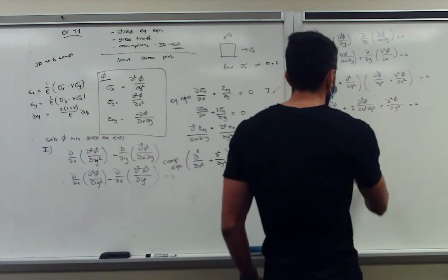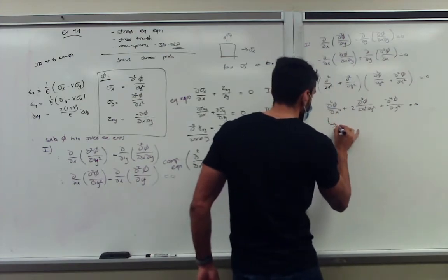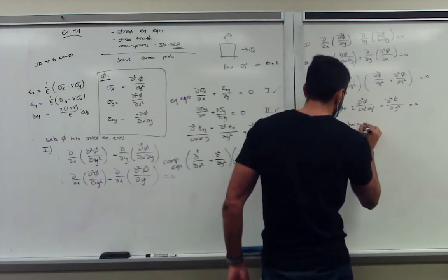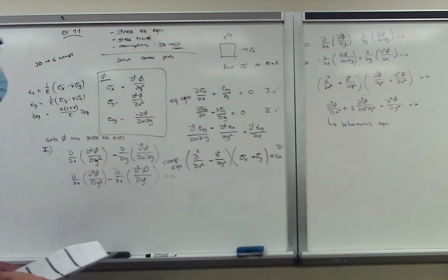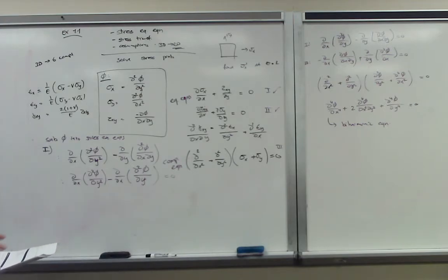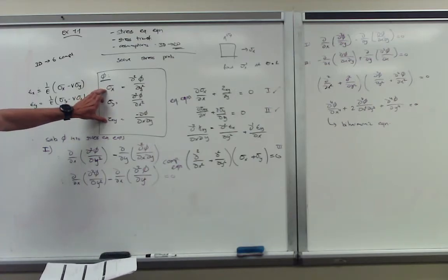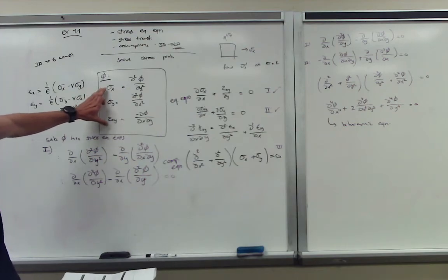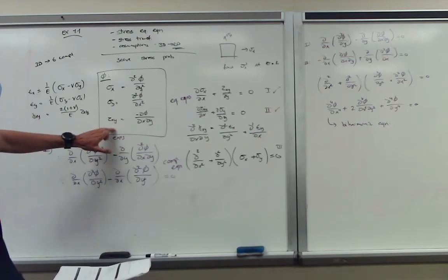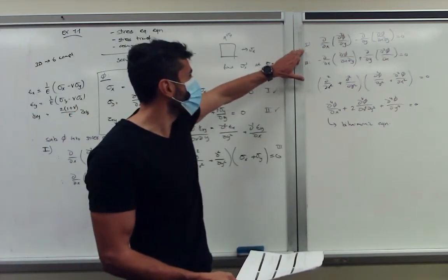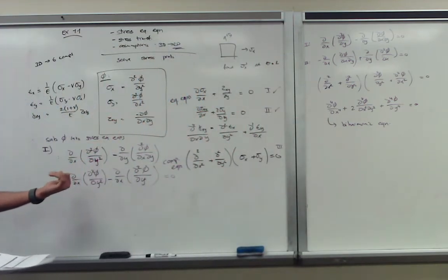And this equation, normally we say it's a compatibility equation, there's a special name to it, and this is known as the biharmonic equation. So now what I can do is look at my problem and define a function that satisfies these three conditions. Based on my function definition, I get my stresses sigma x, sigma y, and tau xy. And I check it with my stress equations and my compatibility equation. This satisfies. It basically gives me a correct solution.